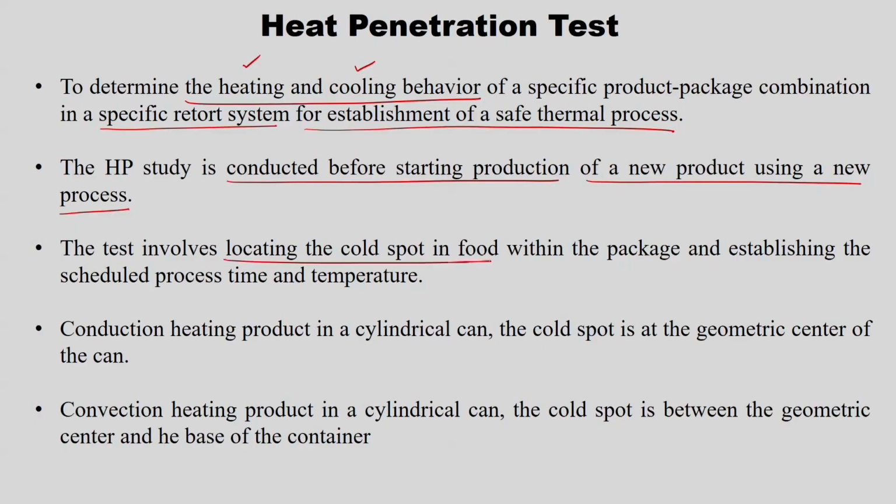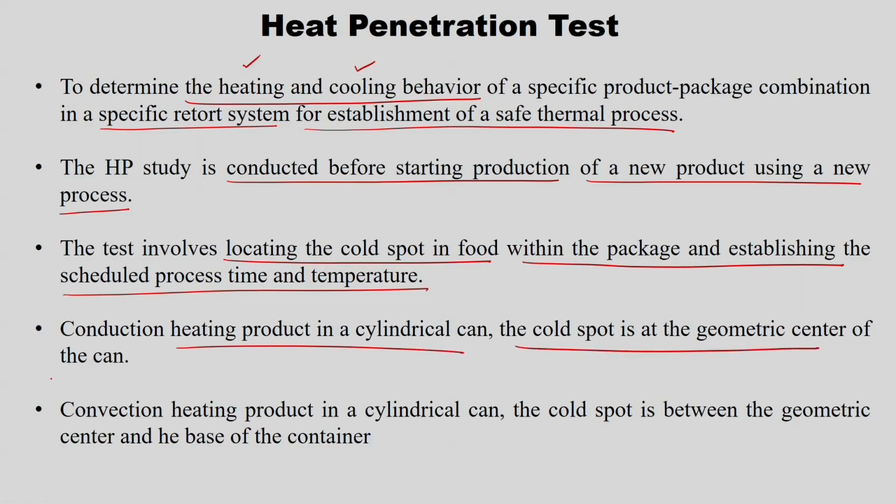If it is an inline thermal processing, then you can go for the heat penetration test. The test involves locating the cold spot in the food within the package and establishing the scheduled time and temperature. For a conduction heating product in a cylindrical can, the cold spot is the geometric center of the can. This I think we have probably discussed already.